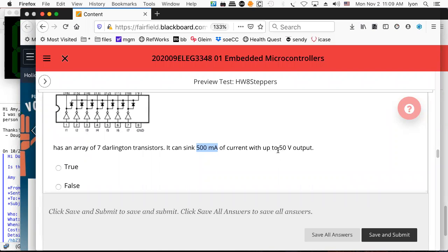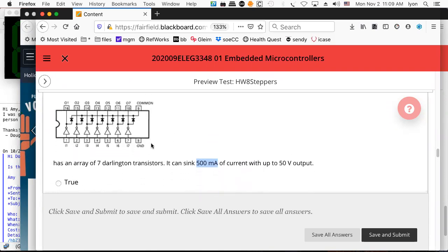Anything after about 50 milliamps off the 3.3 volt supply basically is unreliable. And even 50 milliamps is pushing it because the little regulators on there are, well, not up to snuff. And that's just the regulator. If you're trying to draw directly from the little 8-bit toaster controller that is the 328P, you'll be sorely disappointed after 30 milliamps. It just won't do it.